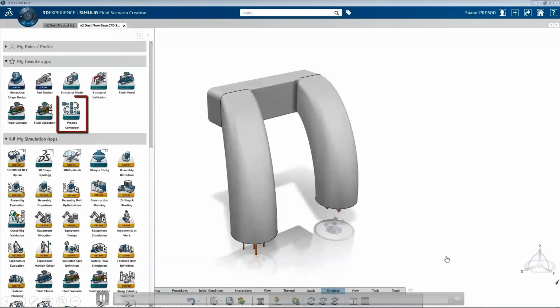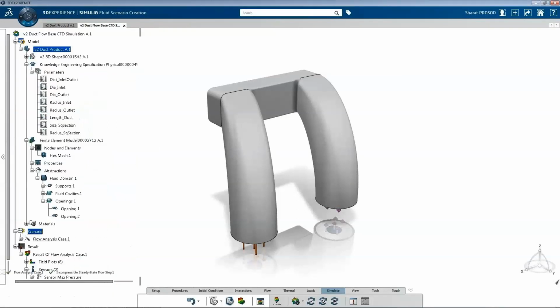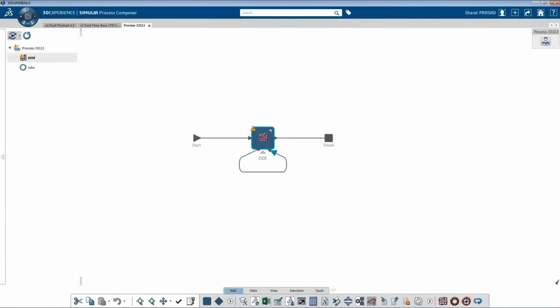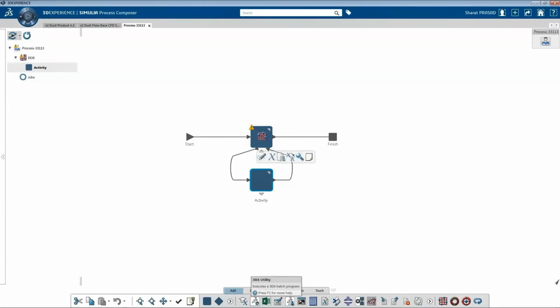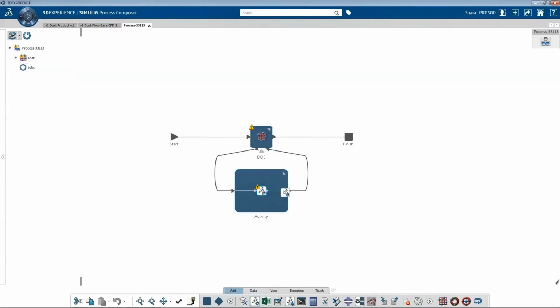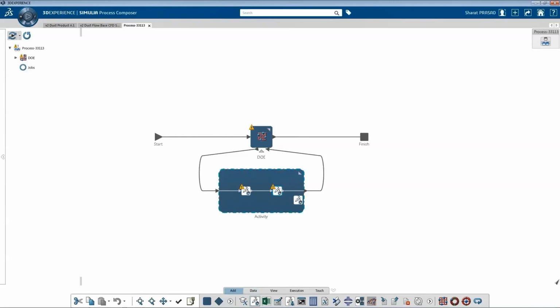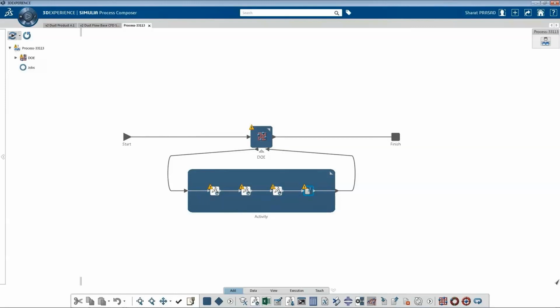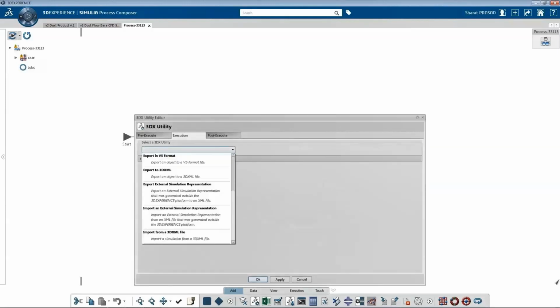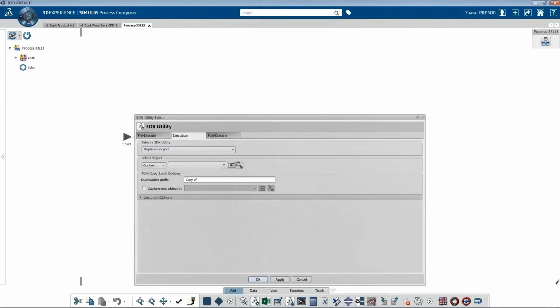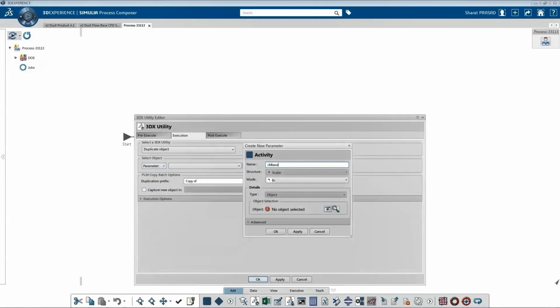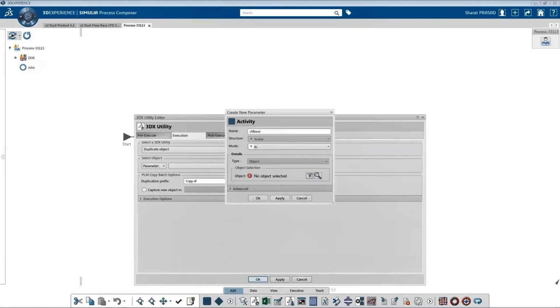These are the different applications on the left-hand side, as you can see. You can use whichever is required at a particular time. This design of experiments works just like Isight. If any of you have used or know about Isight, the same Isight capabilities have been extended onto the 3D experience platform, and the role to carry this out is called the process composer, wherein I can pre-execute, post-execute, as well as execute options, wherein I can set up the model, run the design of experiments, and then validate the results.